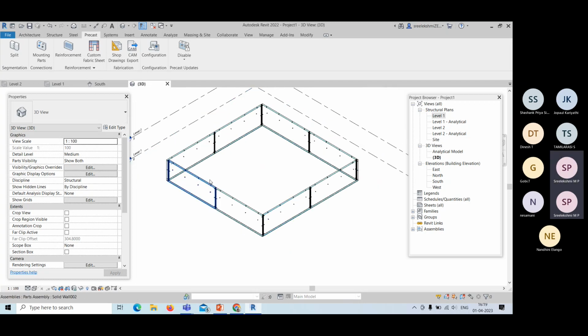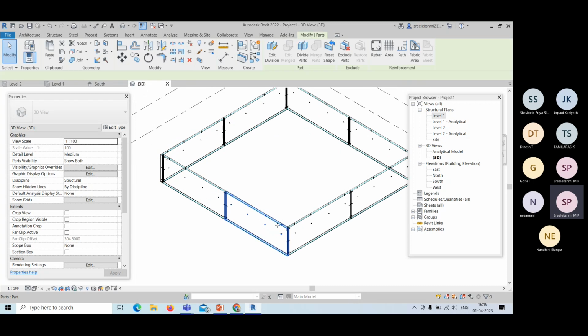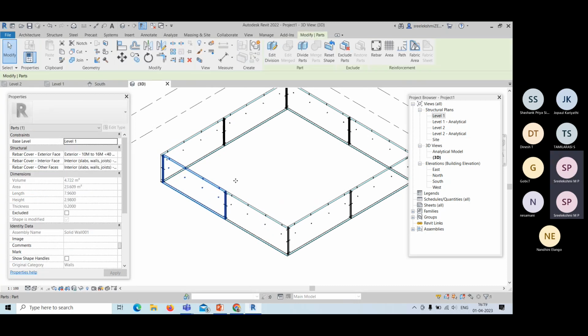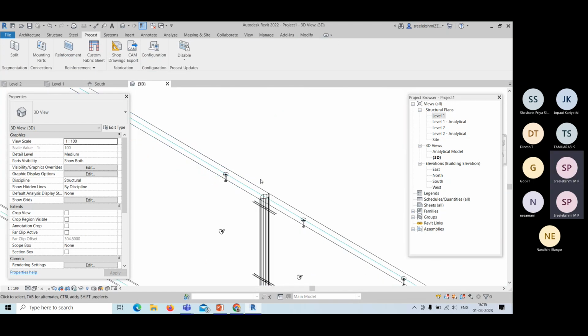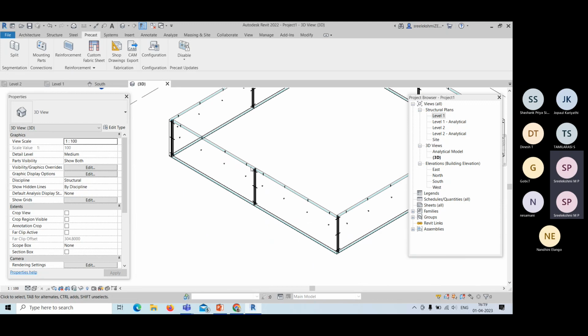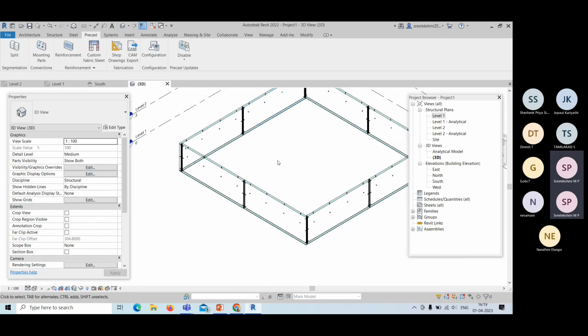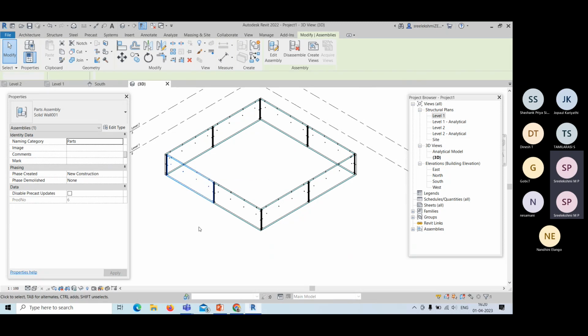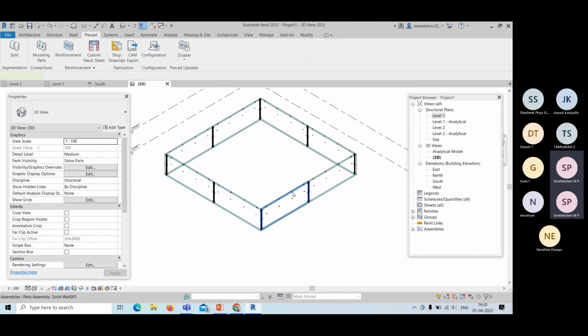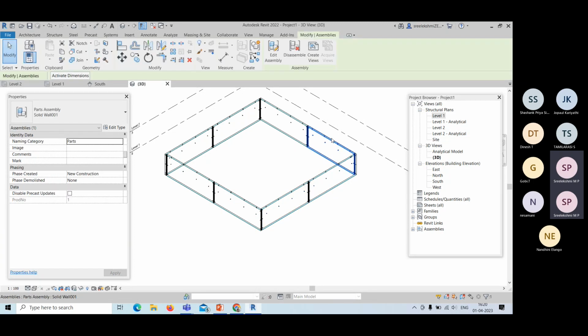Now one side wall is split into two components. Along with that, the connections, that is the mounting parts, are also visible. The mounting parts and the connection elements should be visible only. We can do Show Both, or we can go for Show Parts. Now we have not customized it. It's split according to some default values, right?